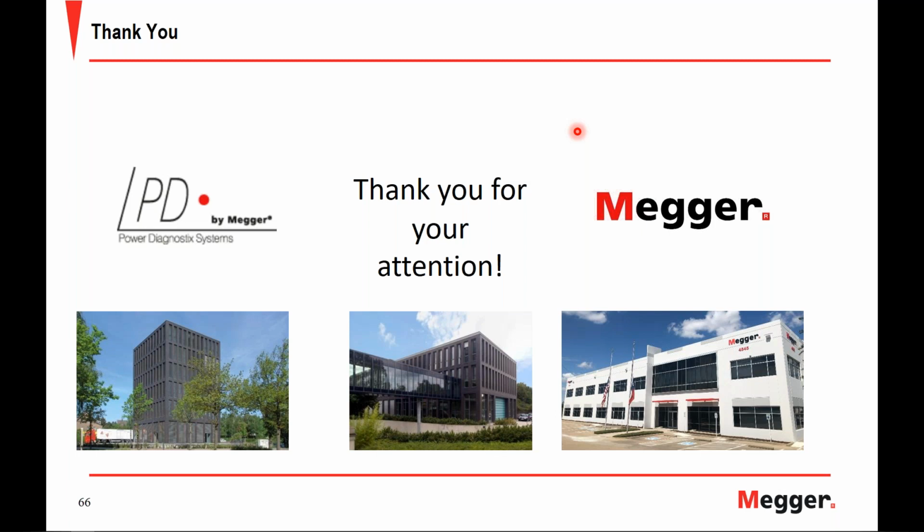On the other hand, you can look at the spectrum, and some activities will come up in a different bandwidth. If you look at the overall spectrum and shift your center frequency cursors along the spectrum, it might be that from one common pattern, you can filter out maybe 2 or 3 individual patterns showing different types of PD activity.